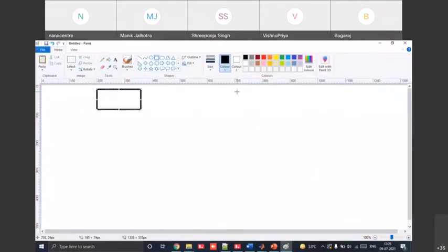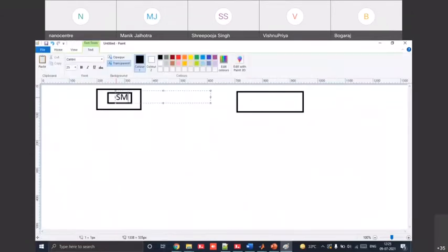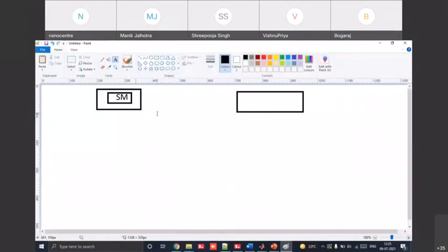Now, in order to tell MATLAB to run the entire architecture which we have developed on the real-time simulator, we make a subsystem and call that particular subsystem SM. So this naming of the subsystem will tell MATLAB to run the code of the model on the subsystem called SM onto the real-time simulator, and this entire information is getting transferred through the cable.